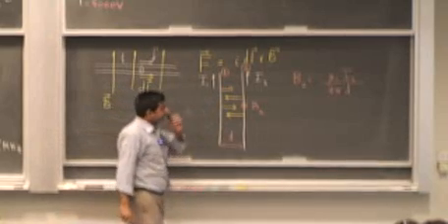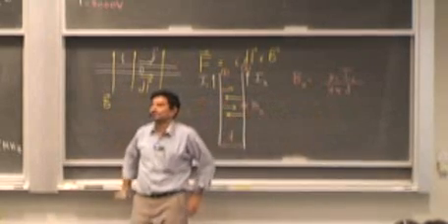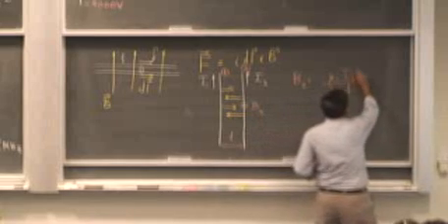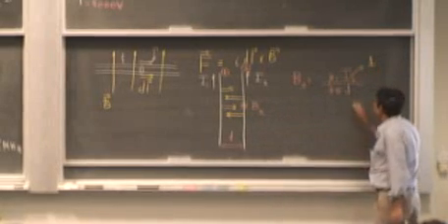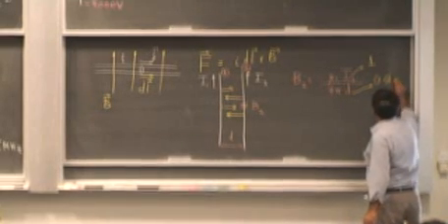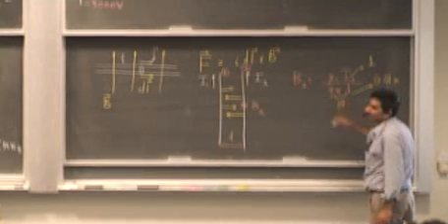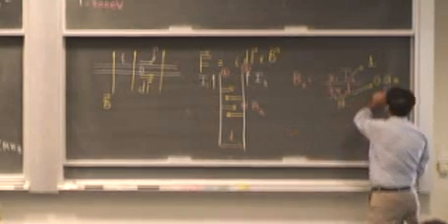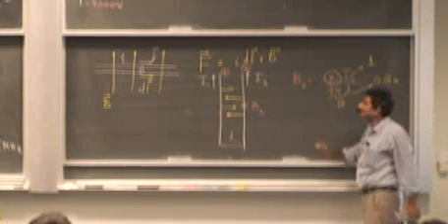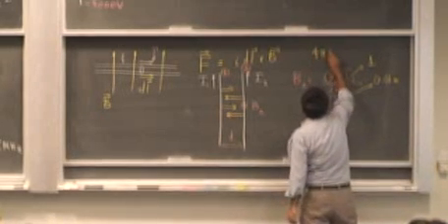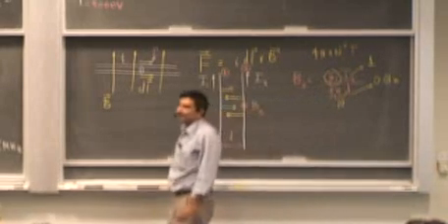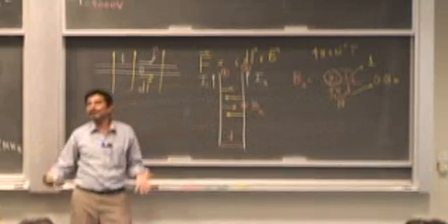Now remember, this magnetic field is extremely small. If this is 1 ampere, and suppose this distance is 1 centimeter, 0.01 meters. Suppose I just take pi to be roughly 10 in the 4 pi. 10 into 0.01 is 0.1. This is 1, so this becomes 10. This is 4 pi into 10 to the power minus 7. So the magnetic field is 4 pi into 10 to the power minus 6 Tesla. Earth's field is 10 to the power minus 4 Tesla, so it's 100 times smaller than the Earth's field.